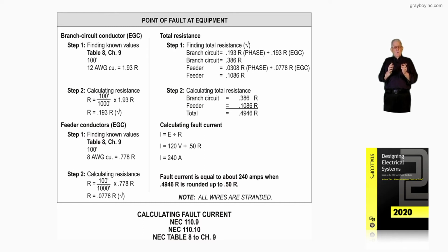And we knew from our experience, you didn't go up to the panel board and short anything out. We'd get all that wire ahead of us with all that resistance in that wire ahead of us, and through bus and everything else and panel boards and all that added together, we'd get a very low available short circuit current. And more than likely, it would be lower than what you see in the calculation. But that's a good method to go by.